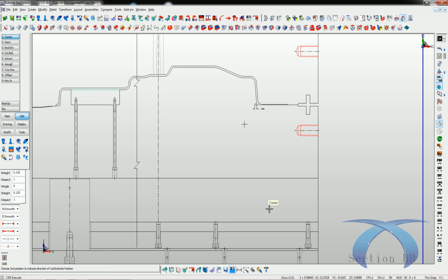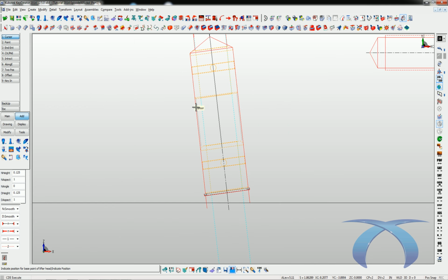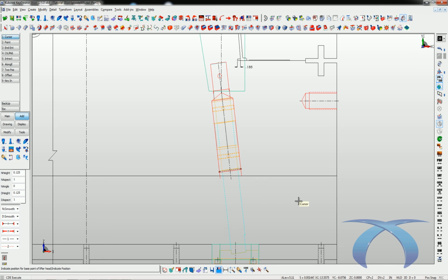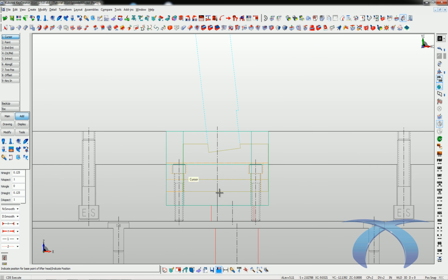And then which direction is my rod going in? So is the rod going in this direction, or is it going in this direction? So it's going in this direction, so I just got to place my cursor over to the right. Okay. And then it goes ahead and generates a basic lifter head for me. And as you can see, it's put in my bushings, my pipe spacers, my retainer rings, my material list will be all up to date, and my entire lifter gib assembly.